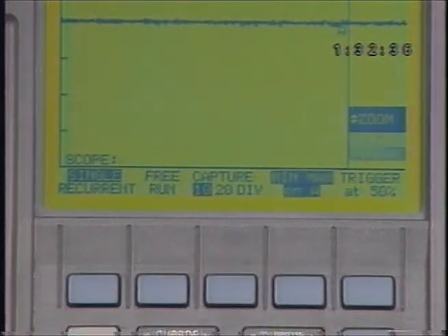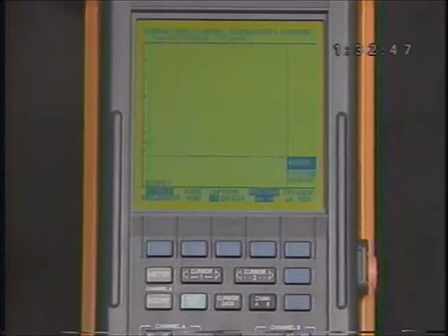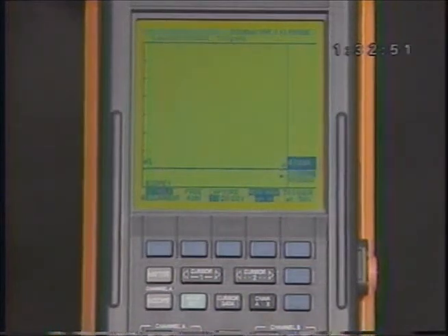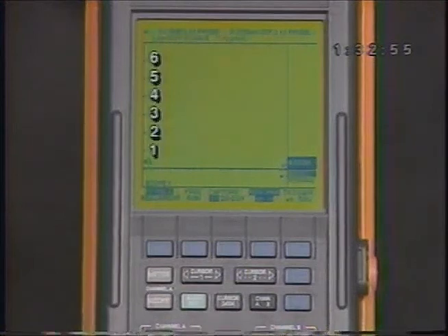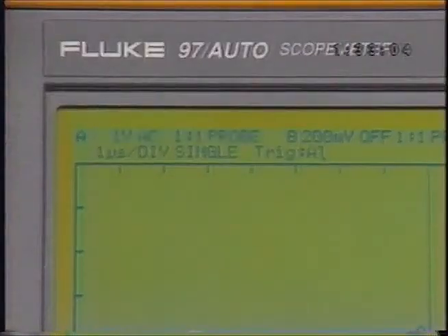Choose Min-Max on A. This increases the sampling rate to Scopemeter's highest level. Set the ground level to the lowest voltage division and use the higher voltage you recorded earlier to set the voltage scale. Since the simulator puts out close to 5 volts for this test and you have 6 divisions above the ground level, 1 volt per division will spread the sensor sweep over the largest area of the display. Then set channel A to DC coupling.